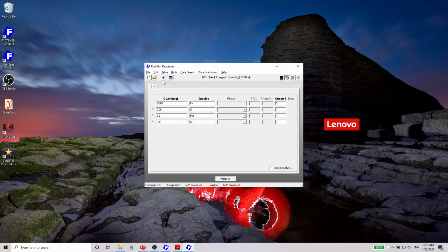After that, we have to add the gas species. The same thing as we have done for steel composition, we have to do for the gases. Here first we input the species names, CO and CO2. Now for gases, the total amount we want to take is 1 mole of gases. So we'll vary the carbon dioxide amount, and then with the varying CO2 amount, the corresponding CO amount will vary accordingly. To do that, first we'll add a variable A,